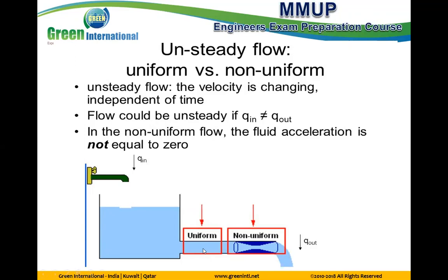Why is this the case? Check with me. The flow here is going down. The level is decreased. We will study in today's session, after some slides, the continuity equation, and after that the Bernoulli equation. The Bernoulli equation is the direct function between velocity, pressure and elevation. If you apply the Bernoulli equation in this case of the tank, what is the velocity at the exit, at the orifice? We will find at the end the velocity equals root 2gh.